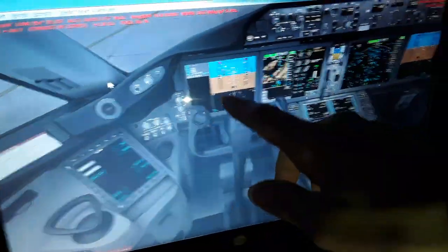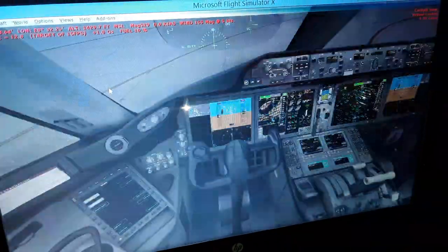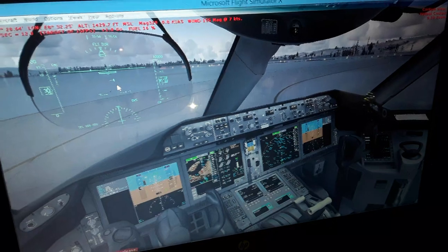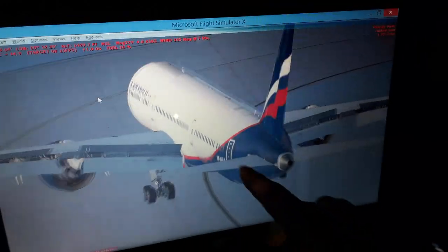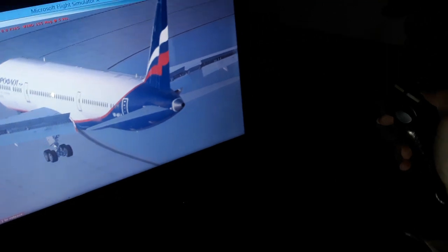manual trim. You can see how many degrees you pitch up the aircraft, you trim the elevator up or down over here in the display. Also you can see the elevator over here is the left and the right horizontal elevator. So when we move the side stick or the yoke of an aircraft for climb descent, you can see the elevator moving. We have also the elevator trim.